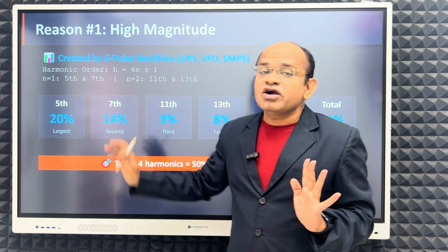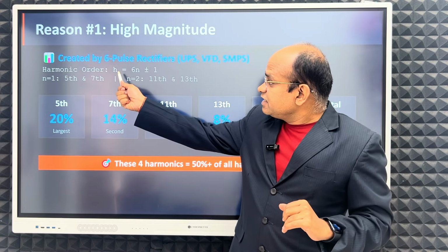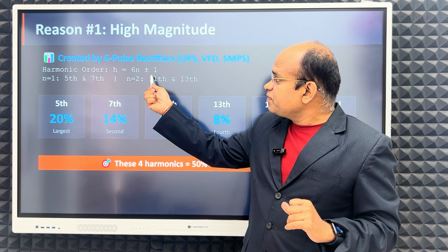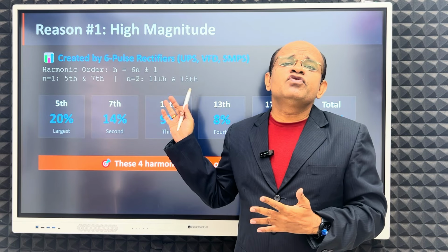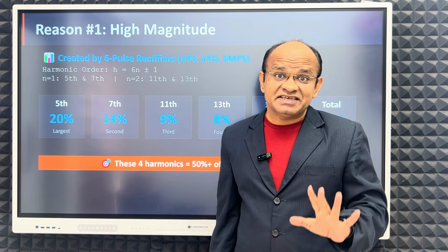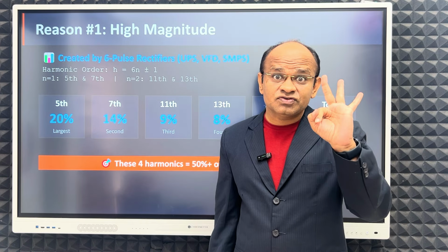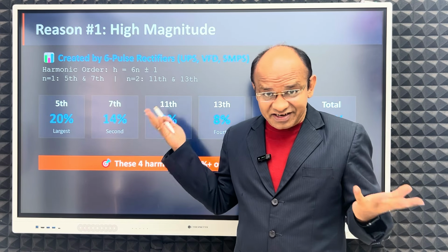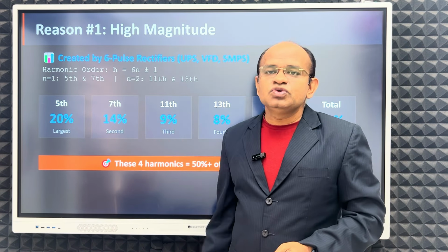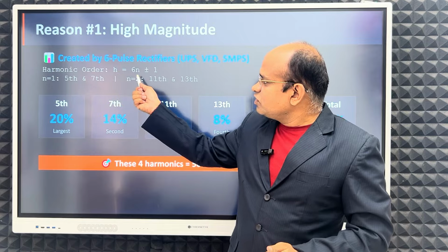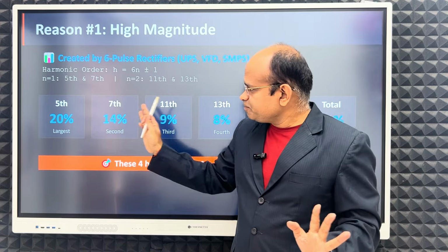Now, harmonic order: h is equal to 6n plus or minus 1. This comes from the Fourier series in mathematics, in engineering. In Maths 3 we have seen the Fourier series. That is what is used here. h is equal to 6n plus or minus 1.